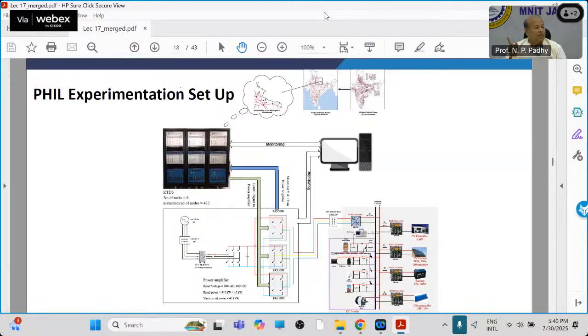Rishikesh, which is a 400 kV bus. There is one bus which is a 400 kV bus in Rishikesh. That I will simulate and then bring back to 230 kV in Haridwar, then 33 kV in Roorkee, and 11 kV of the campus, and then the electrical engineering department microgrid will be a physical one. All the rest will be simulated. So the IIT Roorkee microgrid will be connected to a 400 kV bus of India and the system will be simulated. That is what I have attempted.